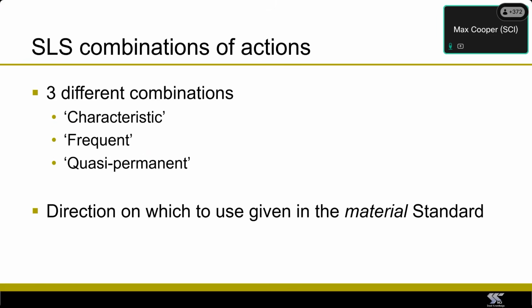Quickly look at the serviceability combination of actions. There are 3 different levels to look at. We look at characteristic, frequent, and quasi-permanent. And the time that we need to use these different combinations is not actually specified in EN 1990 or 1991. It's actually given in the material standard.